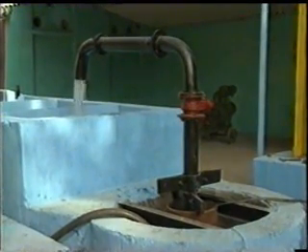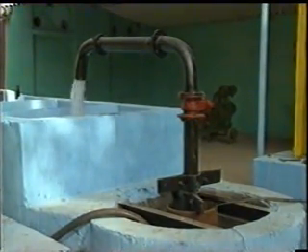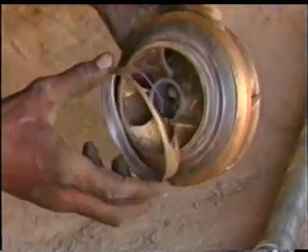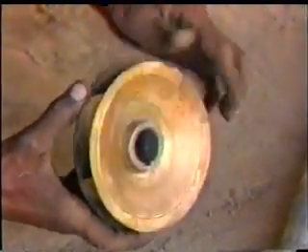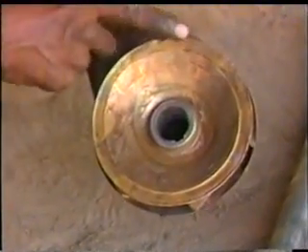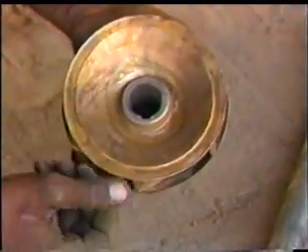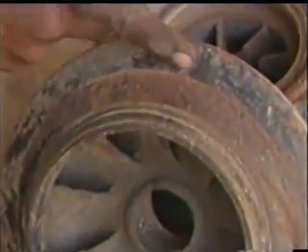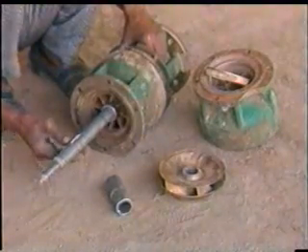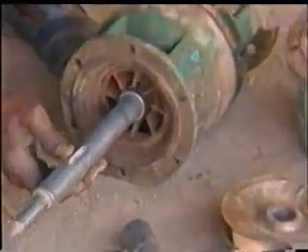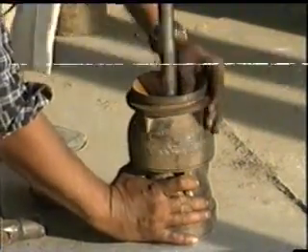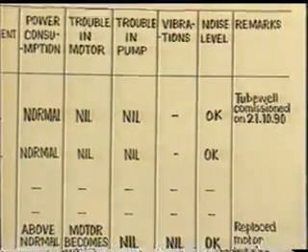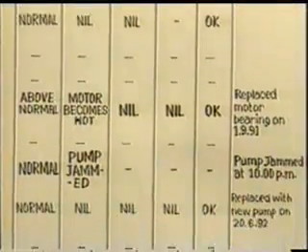Decline in pump discharge and head may be due to defects of pump or both well and pump. The problem in pump may be due to wear and tear, erosion or corrosion of the impeller or bowls, or due to improper adjustment of impeller. The problem is corrected by adjusting the impeller or by repairing the pump. The cause of problem should be made a part of permanent well record.